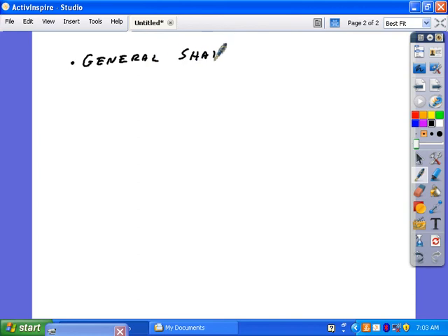The big thing that you're going to notice with most trusses is that they are going to be, in general, a series of triangles, one after the other. Now, the way that I normally simulate why they would want to use a triangle is consider having yourself a pile of popsicle sticks. And the only way that you can connect those popsicle sticks to each other was by driving a nail through one end into the other. Okay? If each one of these was a popsicle stick, we had one nail pinching these, one nail pinching these, and one nail pinching these, this structure would be upright.